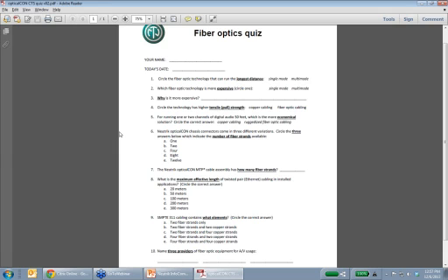We really skipped over number 9. So you might only know this if you already knew it before coming in. But SMPTE 311 cabling is 2 fiber strands and 4 copper strands. Again, 2 for power, 2 for sense operations. That's number C. Letter C. And 10, your 3 providers of fiber optic equipment. Again, this could be Crestron, Extron, AMX, Fiberplex, Telecast, Telemetrics, Think Logical, a ton of different providers.